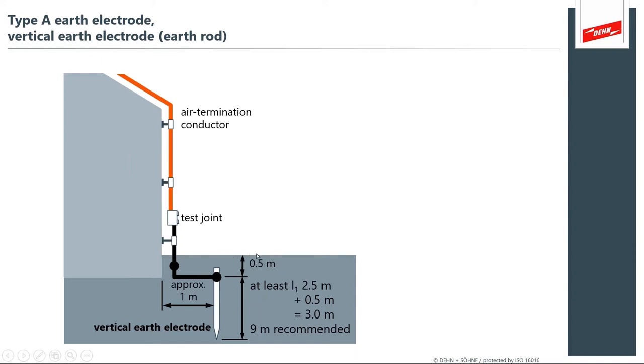This helps prevent ground potential rise and touch and step voltage issues. It also helps avoid things like frost heave. But again, this goes back to part of the overall design of the system, so that the earthing system meets the expectations and requirements of the design.